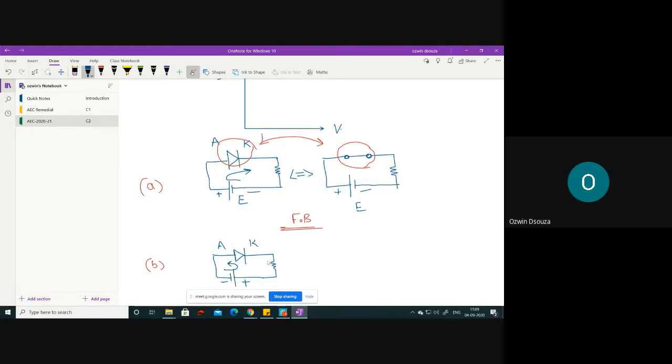This depletion region can be regarded as an insulator, so it is similar to an insulator. The greater the width of the depletion layer, the poorer the conducting properties. So in the reverse biasing mode, the depletion layer thickens, due to which the diode stops conducting. Stops conducting means zero current, right?